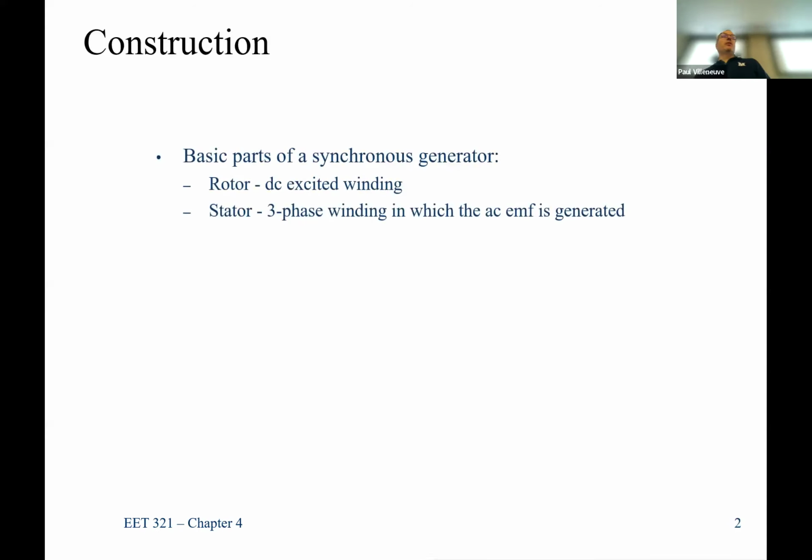So how do you build a synchronous machine? Or a synchronous generator? We should be specific about generator because a motor and a generator are different. But the stator is exactly the same as what we covered last chapter. When we looked at those three windings, it's exactly the same. And then you have a rotating MMF, or rotating magnetic field, that when you add load to it, when you pull current out of it, you actually get that back EMF voltage that's generated. The difference is now we're looking at the rotor.